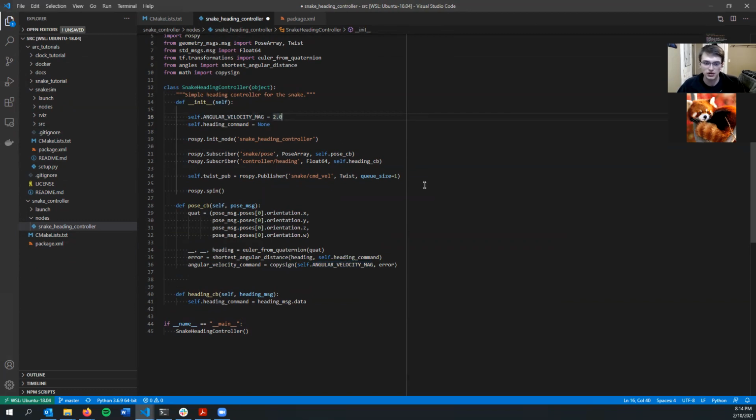You could convert that into RPM, or how many revolutions per second, if you wanted to, but that's an arbitrary speed that we just picked. Then we're saying give it the sign of the error. So if we're facing one direction, make it the one that would bring us to the center. You could do that by working out the math for that, or you could just try it, and if it's wrong, stick a negative there.